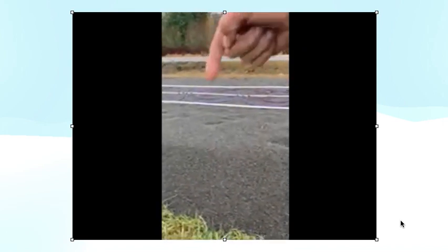So even though you have your coils level, gravity doesn't stop being in effect. Water will still go where gravity pulls it. And so if you have marginal soil and this isn't installed on contour, then you'll have water end up coming to this bottom corner right over there and potentially ponding there. That's not okay, and that doesn't happen when these are installed on contour.